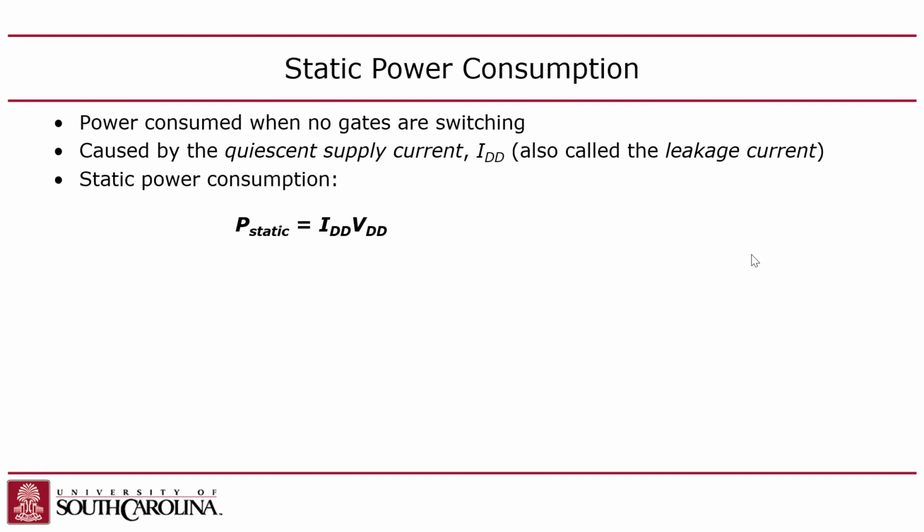And then static power consumption is a little harder to quantify. It's basically just the leakage current multiplied by the voltage. And it's harder to measure the leakage current. That depends on the transistors and how much current the transistors are letting through. And that really just depends on the off resistance, right? Because when the transistor is off, it's not really off. It just has a high resistance value. It's R off, right? It's like a 10 mega ohm resistance. Does that make sense? So you're going to have some leakage there even through transistors that are turned off, just very little.